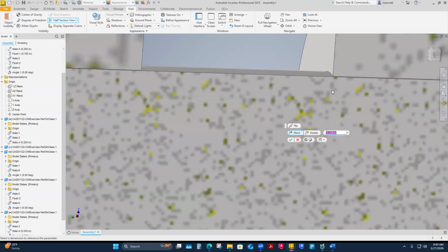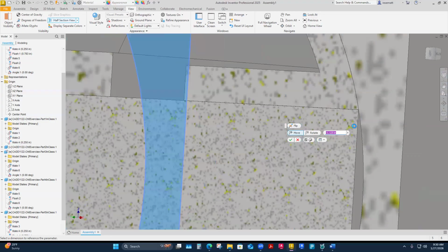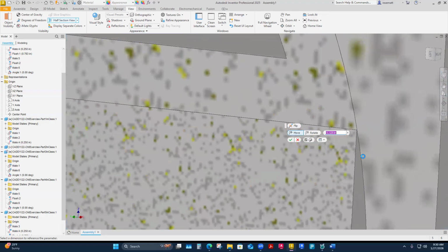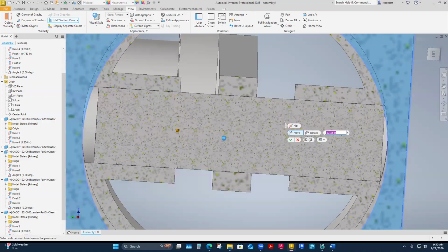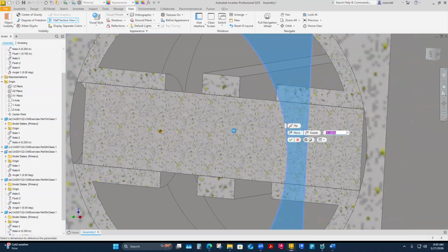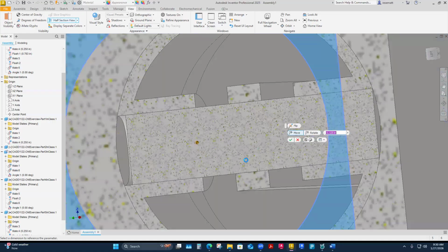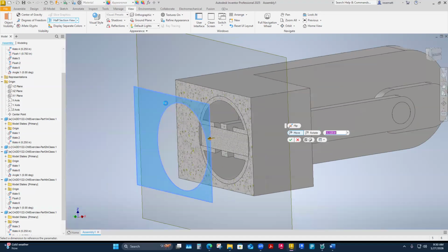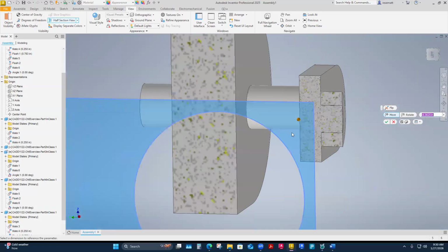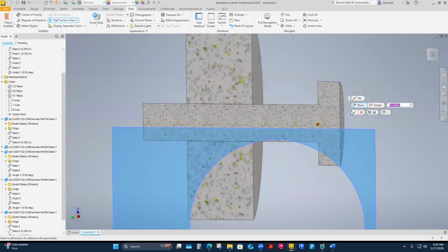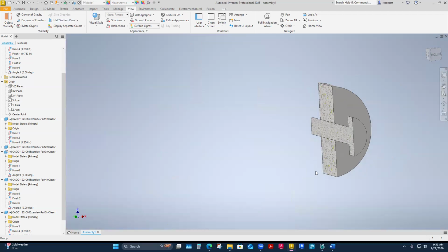But I get an idea that, look, this is going to be size on size. There's no tolerance applied. There's a very small likelihood that these parts would actually fit together, especially if you're going to 3D print them, and there's going to be some inaccuracy in how accurately the 3D printer can make the part. So this is probably not going to fit together without some tolerance applied. But you can cut down through here and see how these parts are fitting together even further. You can save this, I can hit check and it'll save like that. Here's that view.